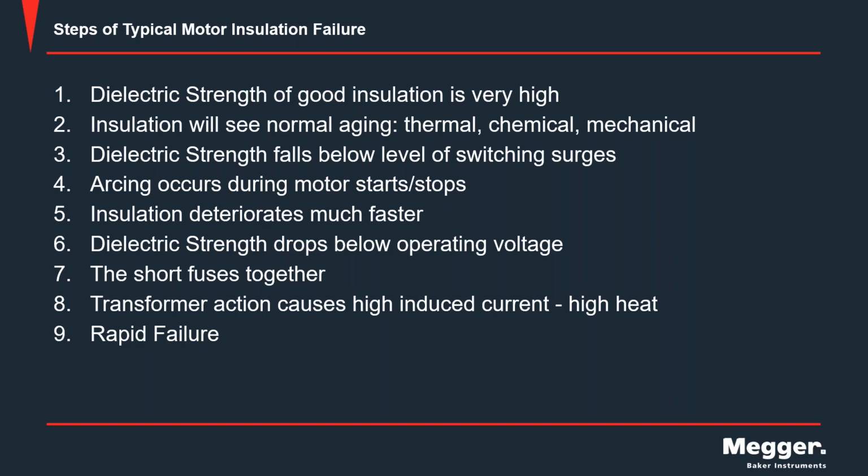So the idea with this kind of testing is to catch it here at step 3. We're going to set our voltages and our parameters at the level where those switching surges occur. We set it at that level so that we get warned, we get a heads up, we get a predictive nature out of this type of testing.